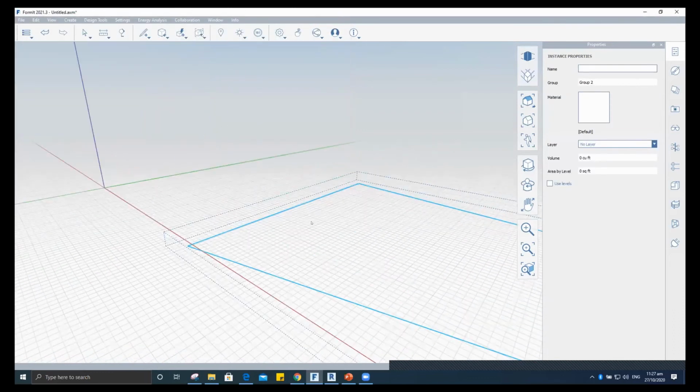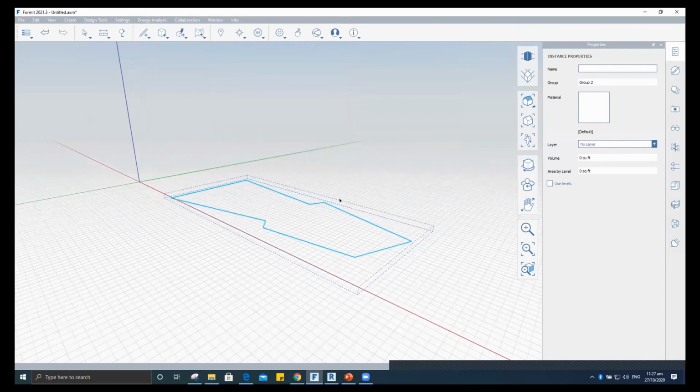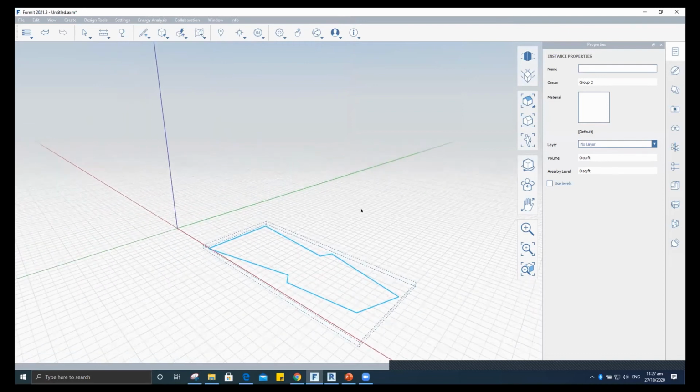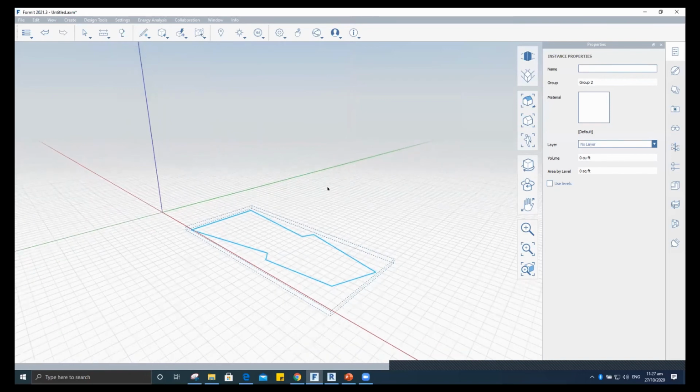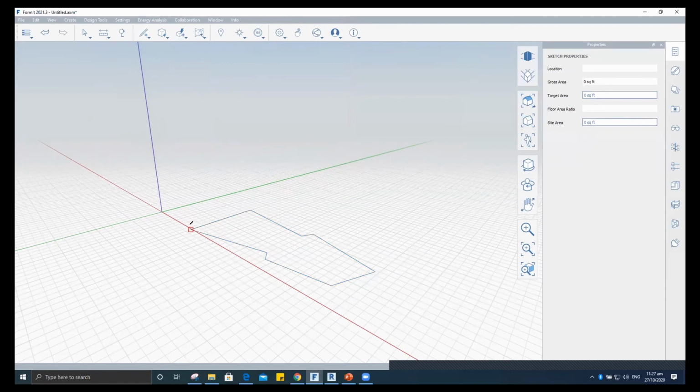Now, our 2D drawing created in AutoCAD, we will use as a reference in order for us to create a 3D model or massing model. Just simply use the geometric intelligent toolset, like for now, I will use this line tool, then I will trace over our 2D drawing. You can see how simple it is to use a reference for our project.